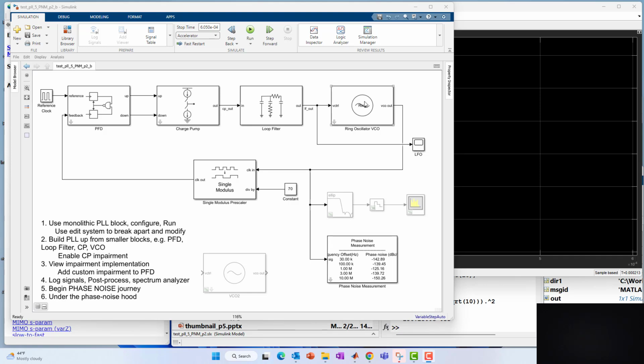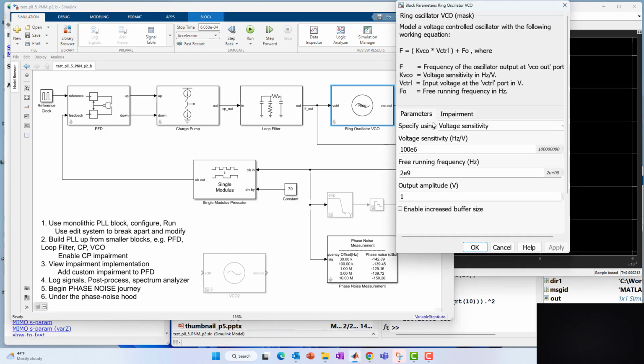But going further, we're going to show how to look at what are called callbacks associated with the blocks. For many blocks in Simulink, you can optionally put a mask on the block, which is what we've done here. That's why, when you double click on the block, you see a mask and not the implementation details.